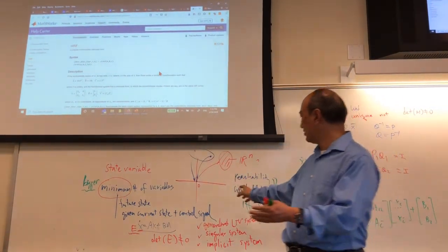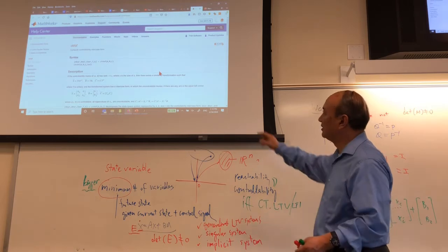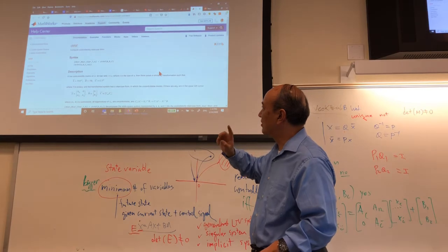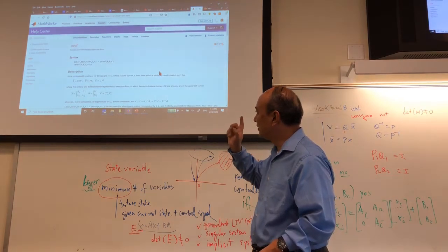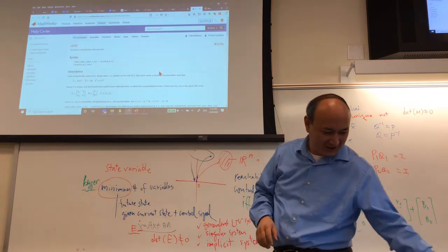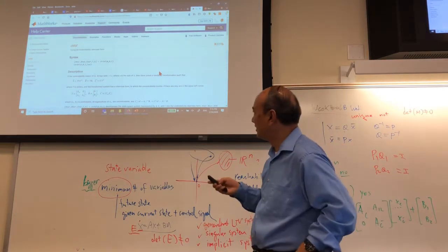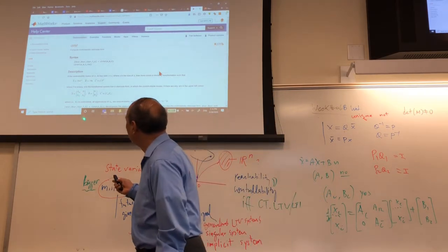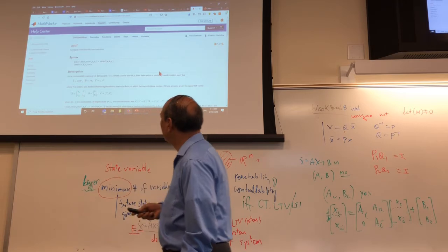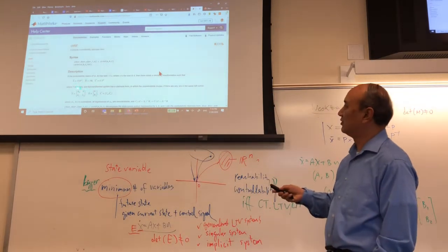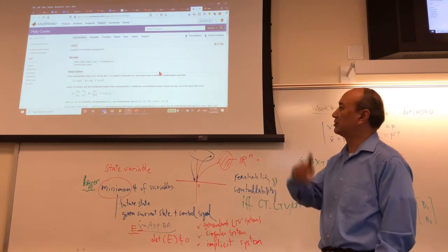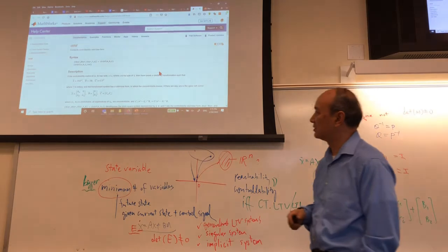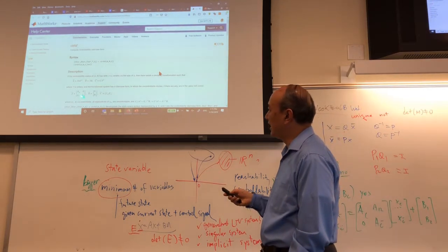So you give it the original system A, B, C, and it is going to give you back A-bar, B-bar, C-bar, and T and K. Especially that T matrix is interesting, since it gives you this T directly. So this is A-bar, this is A-c-bar. This is called staircase for lower triangular, but people also do upper triangular. This is just the transpose. So we use the upper triangular.